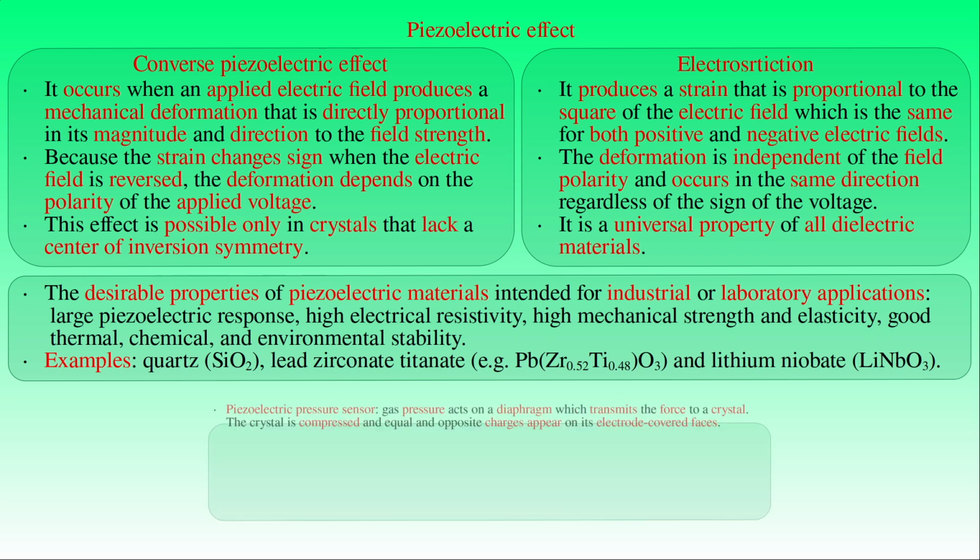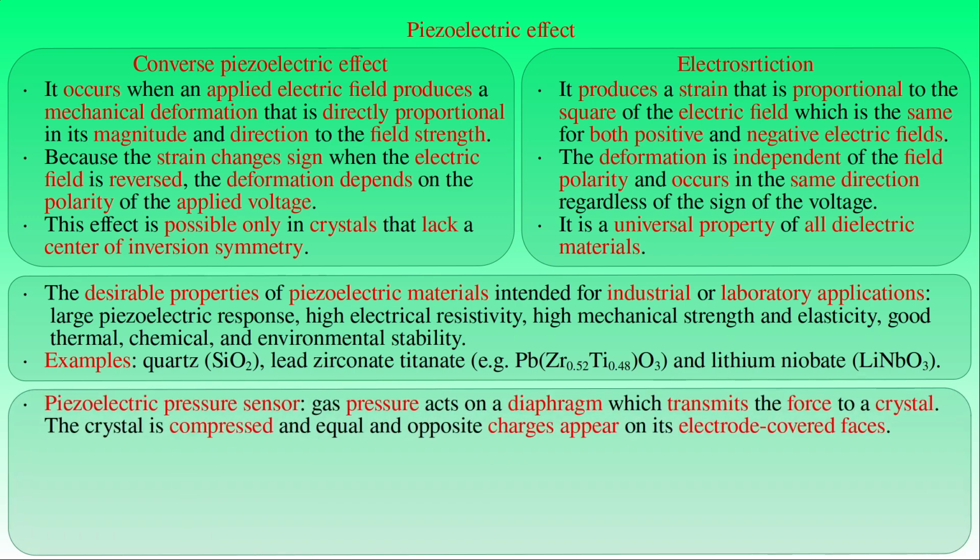One of the most typical applications of this effect is the piezoelectric pressure sensor or manometer, designed to measure fast variations in pressure. When the pressure of a gas in a vessel acts on the diaphragm of the manometer, the diaphragm transmits a force to the crystal installed as a sensor, which is a quartz or tourmaline crystal or a piezoelectric ceramic such as lead zirconate titanate. The applied force compresses the crystal, producing an electric polarization, and, as a result, equal and opposite charges appear on the electrode-covered faces of the crystal.